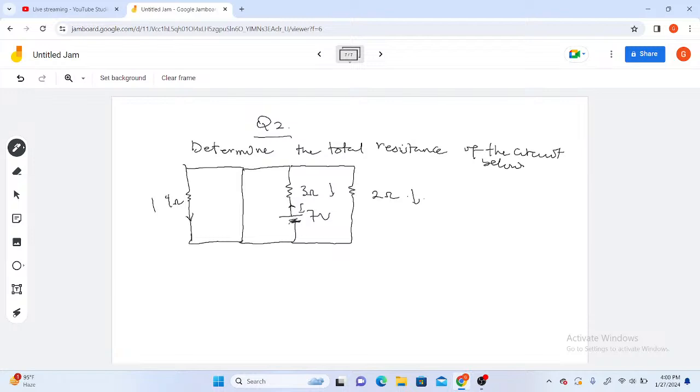You ask yourself, from the conditions I stated, we take 2 resistors at a time. So 2 resistors at a time. For that reason, we are going to consider 2 resistors alone. Now, the second part is you are to simplify resistors away from the source. Then we gradually come to the source, right? So now let's see. I'm having this 4 ohm here and this 2 ohm here away from the source. This 3 ohm here is directly at the source and we can't consider it at the first. So we only consider 4 ohm here and the 2 ohm resistor here.